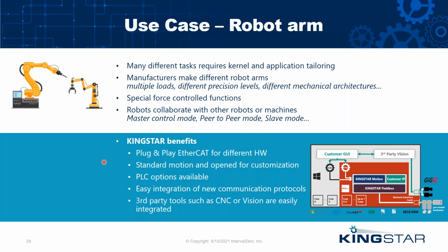The easiest method is to write only one application in the controller of the CNC. To do this, both controllers need to have the same way to communicate. This is often possible because both CNC and the robots implement a standard PLC. So instead of writing the application in the PLC of the robot, you write that application in the PLC of the CNC, and that CNC will transmit the command to the robot controller over a real-time protocol.